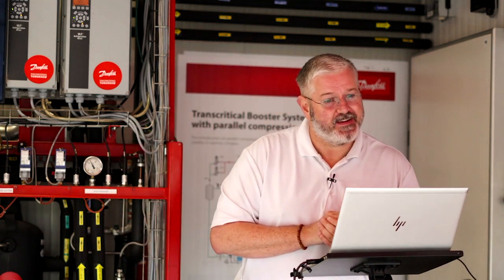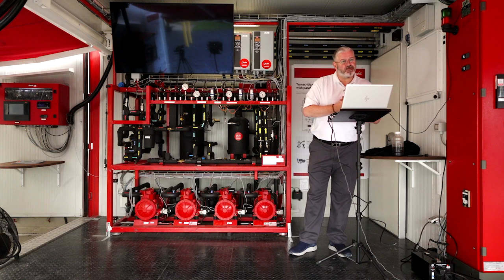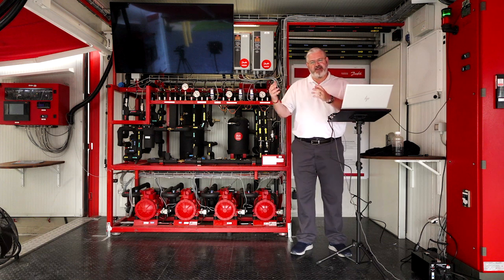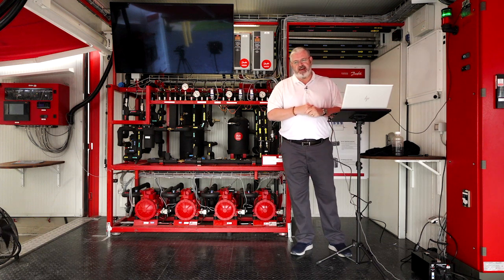Do you have any idea, any data on expected percentage of refrigerant loss per year on a CO2 system? I don't really have data on that. My guess would be the same people that put in the CO2 are the ones that put in the HFC. Whatever percentage leaks you see on the HFC, you probably see about the same on the CO2. Probably a fair guess.